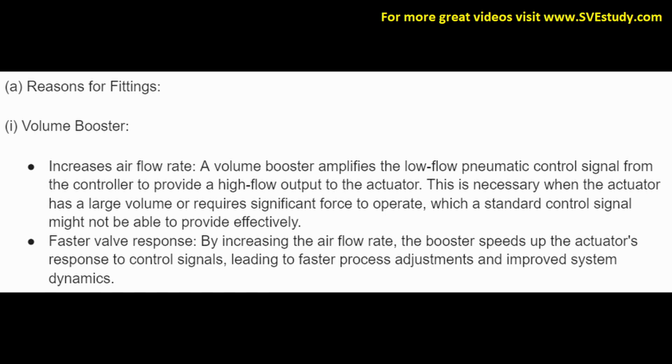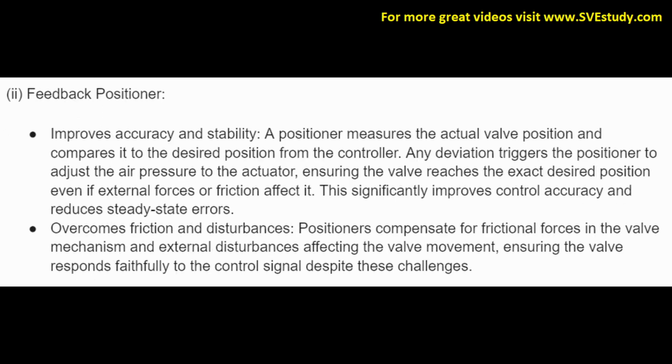This is necessary when the actuator has a large volume or requires significant force to operate, which a standard control signal might not be able to provide effectively. Faster valve response. By increasing the airflow rate, the booster speeds up the actuator's response to control signals, leading to faster process adjustment and improved system dynamics.